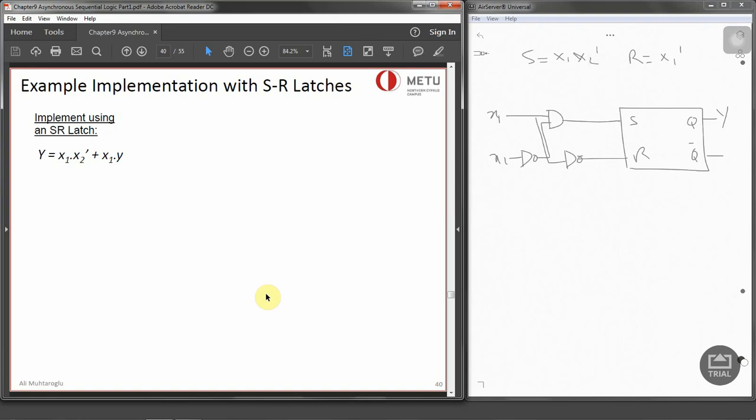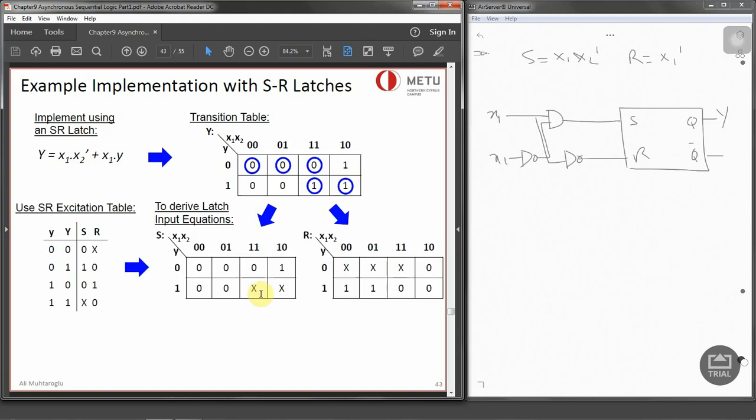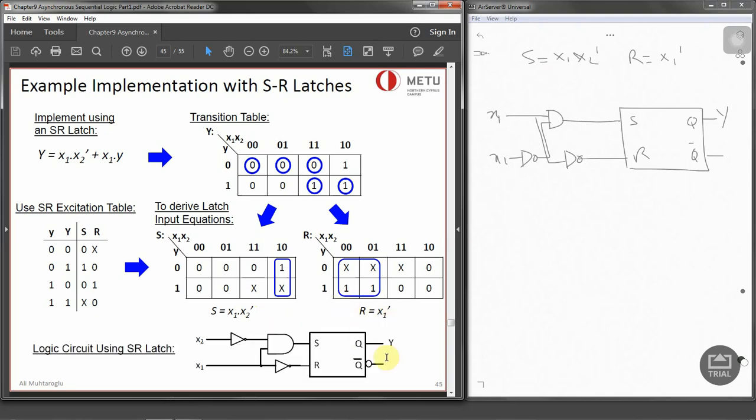If you have any questions related to this, note it down and you can ask me during the question and answer session. And in this circuit, be careful that S and R equal to 1 never occurs by this design. So you can find similar slides of what we have done as an implementation with the Karnaugh maps and the simplification, then the logical implementation of it.